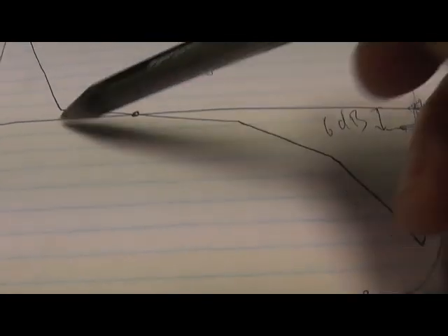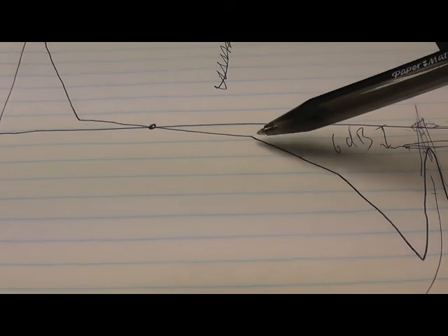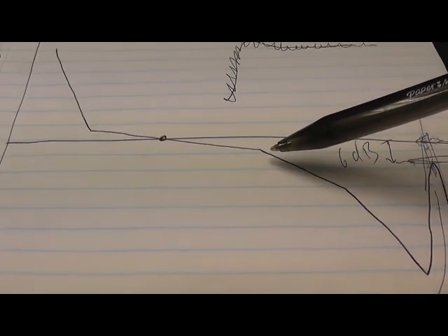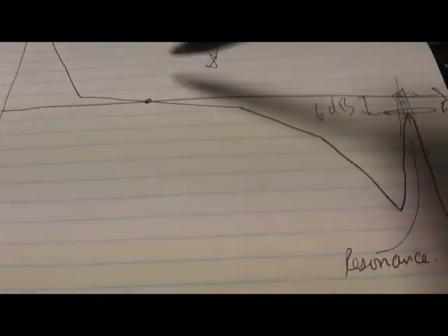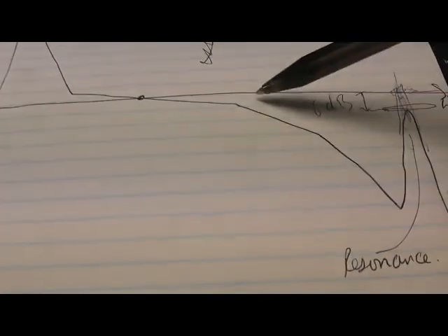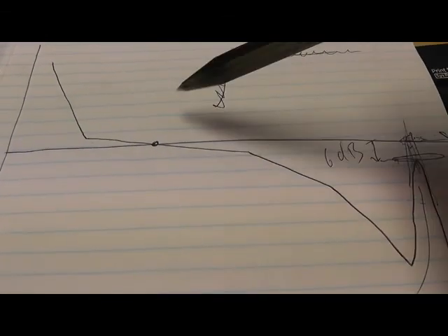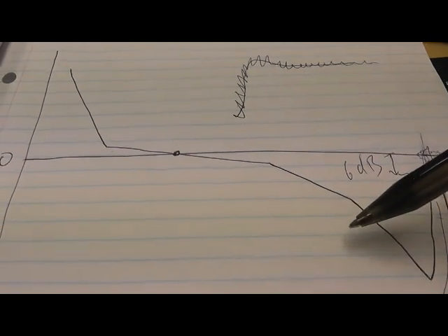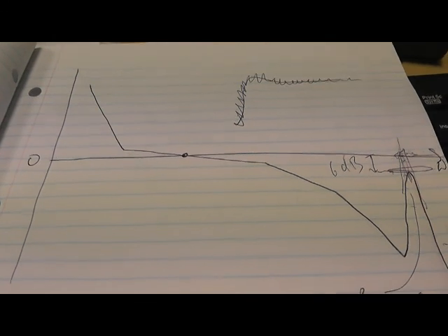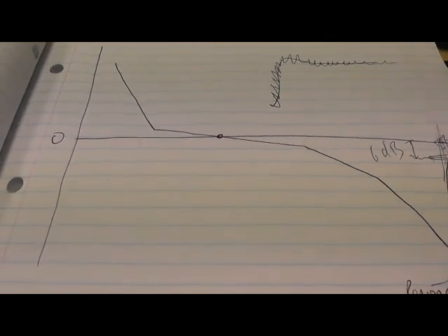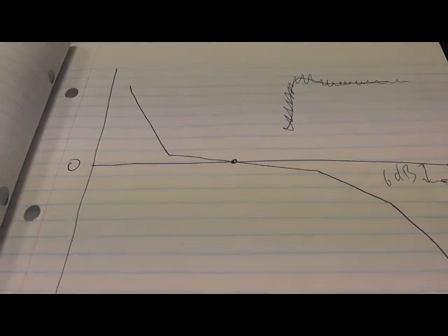So it is possible to go through unity gain asymptotically flat. If you added a second phase advance, that would give you a lovely, amazing amount of phase margin, and you might just be able to manage to squeeze it through, because although asymptotically it doesn't make much sense, the actual plot will cross over and hopefully cross over just once, and it should work. So it's not perhaps unusual to have more than one phase advance if you can get away with it. Just like you can have more than one integrator, why not have more than one phase advance?